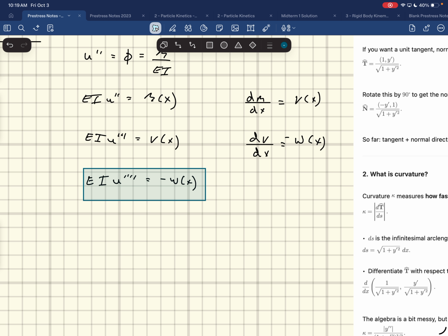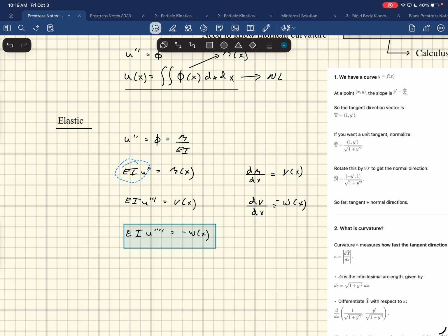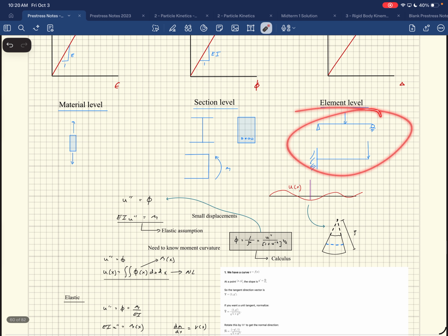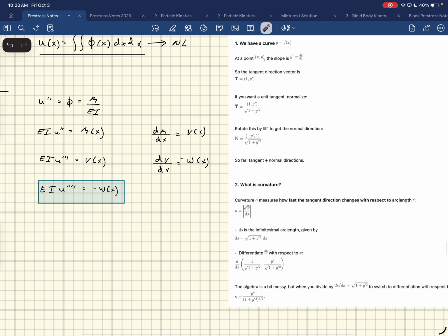But it's kind of cool that it incorporates all of that. I mean, this EI is the slope. It ties back to this relationship, right? The EI is just the relationship between curvature and moment. And then you integrate it across the length of this thing. And then the different types of support conditions get incorporated with the boundary conditions that you use to solve this fourth order differential equation, right? And so it's a compilation of all of those things. It's magical. I think it's a magical equation.